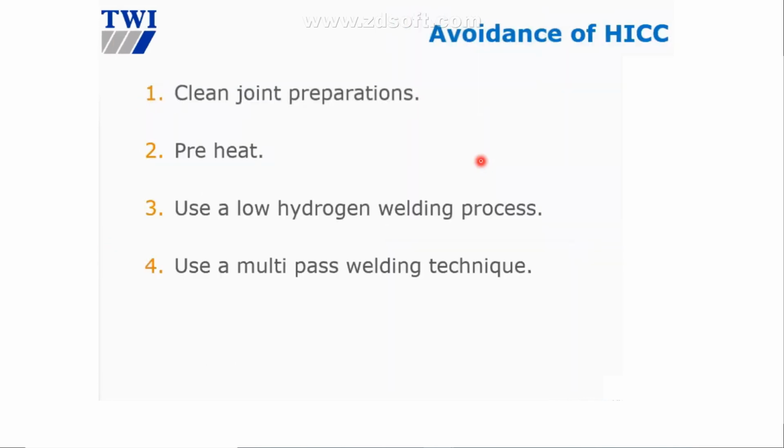All right, how to avoid hydrogen crack? We have 4 factors. Then you need to avoid any one of the factors. Clean joint preparation, meaning removing any contamination.